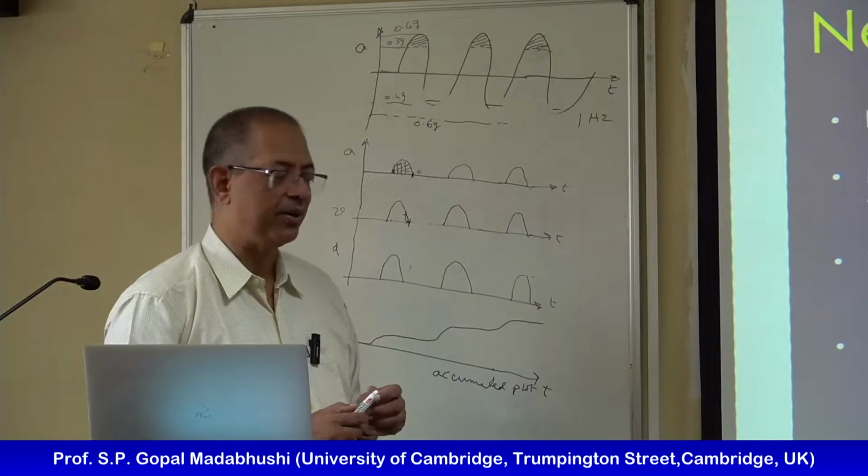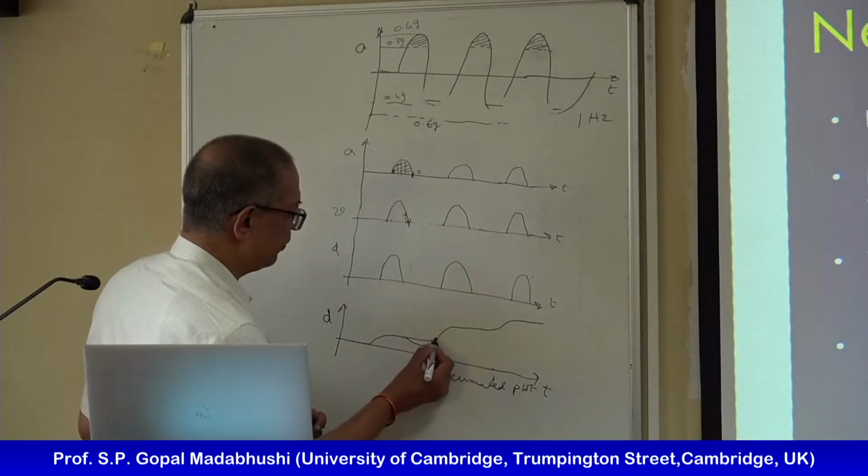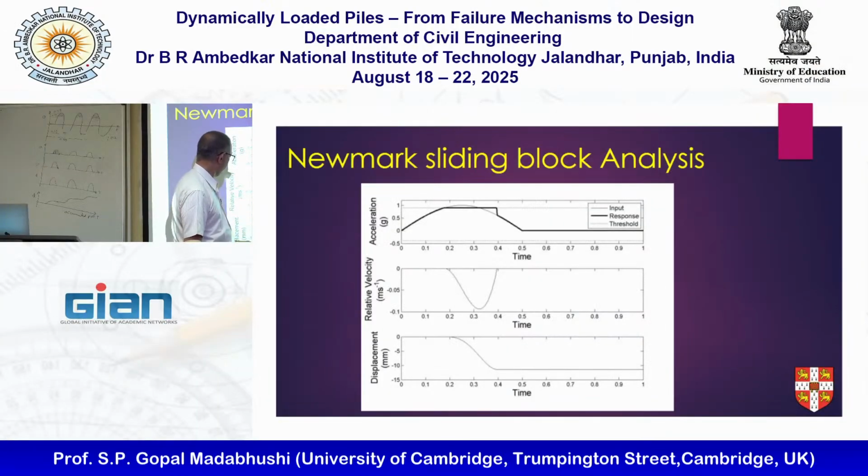So you will get something like a decrease here and then followed by down to zero. And then integrating that to displacement will give you something like that, because I'm always adding to the cumulative displacement. So you get something like 10, 15 millimeters. This is all at centrifuge scale, so you have to multiply that with n. But that demonstrates the principle of it.